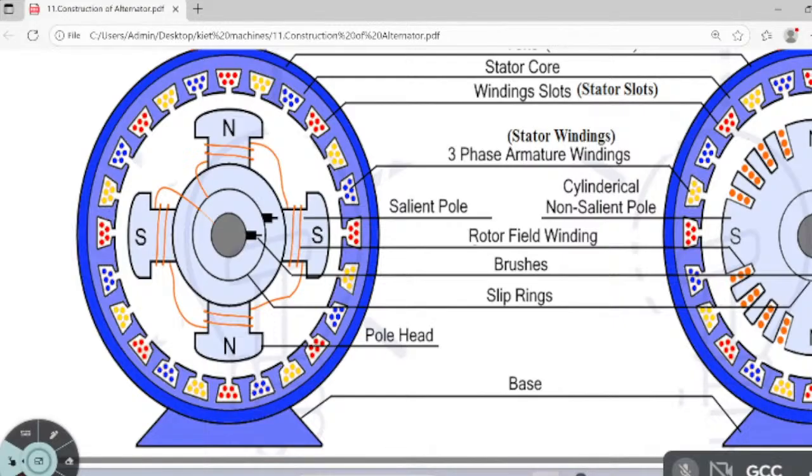Here pole shoe is not like that. Directly, the pole is nothing but one like this. It is made up of iron. We are winding copper wire around this cast iron piece, clockwise, anti-clockwise. Directly it is circular, with equal distance. A separate pole shoe is not required. The pole directly acts to distribute the flux equally to the stator. There is no additional pole shoe required.